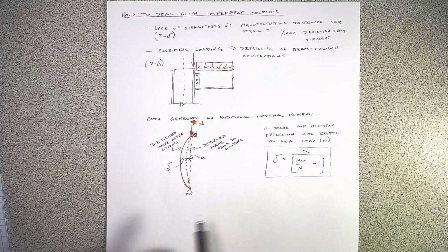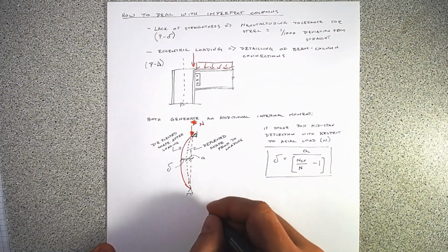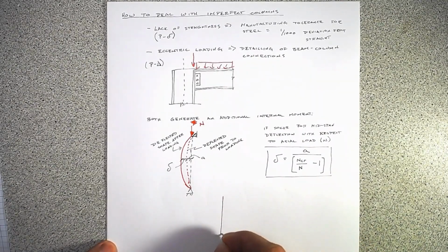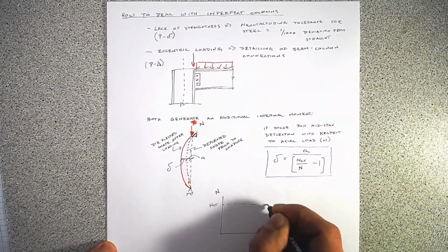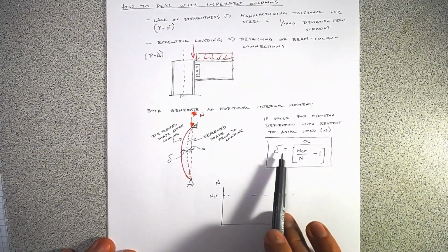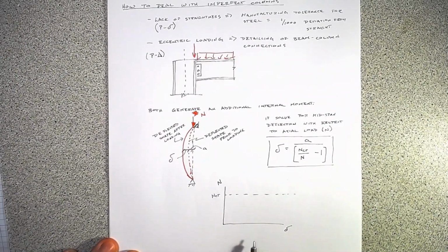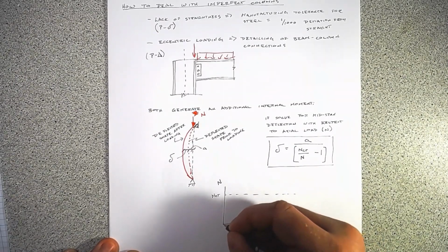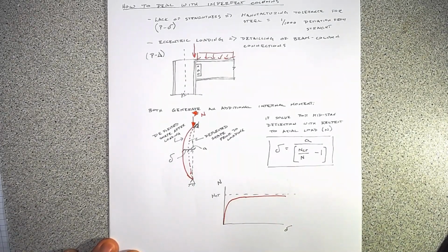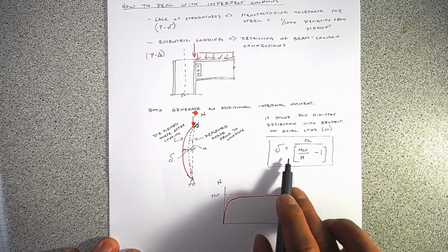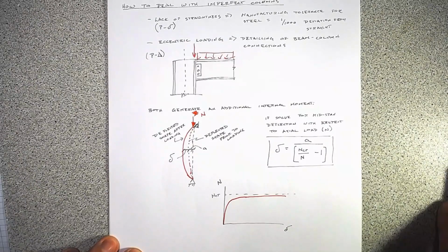And then if we plot this up, on one axis, let's plot this deflection D with respect to N, and let's just put NCR here. So if we were to load up N, as our value N goes up, our deflection's going to go up as well. And what you find is that you get a plot that looks something like this, where essentially you'll go up, and then as you approach this critical buckling load, your out-of-plane deformation is going to rapidly increase. And that makes sense.